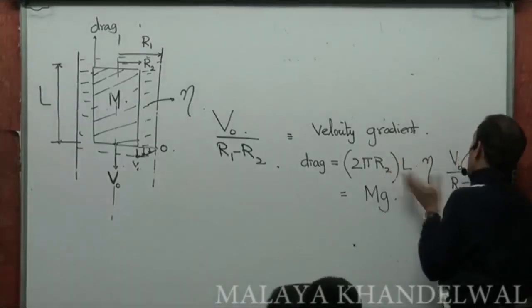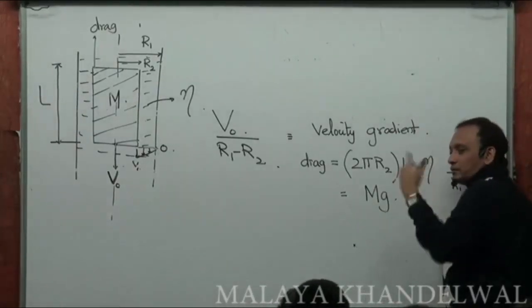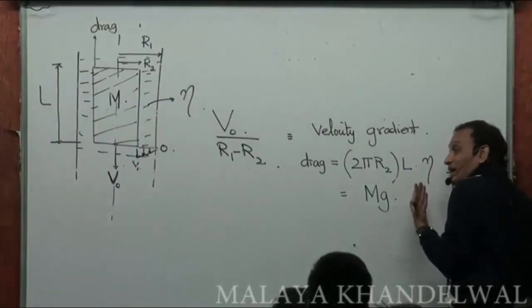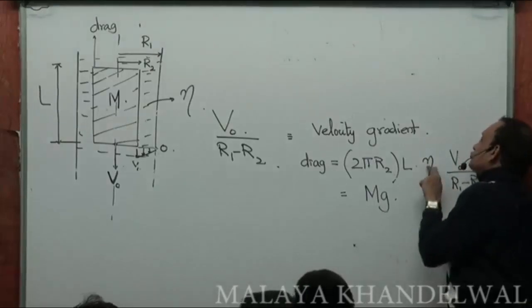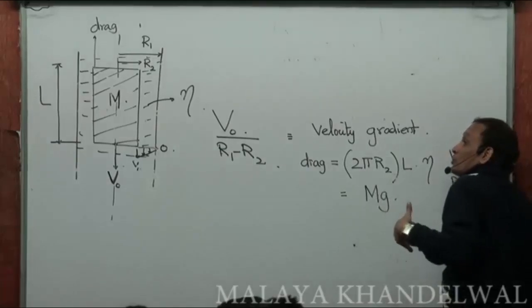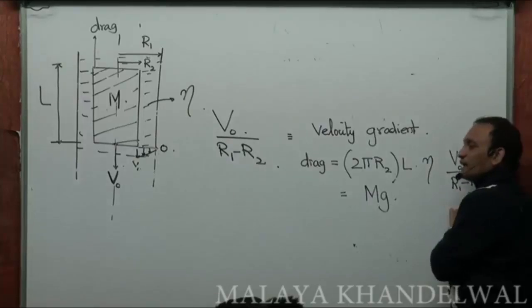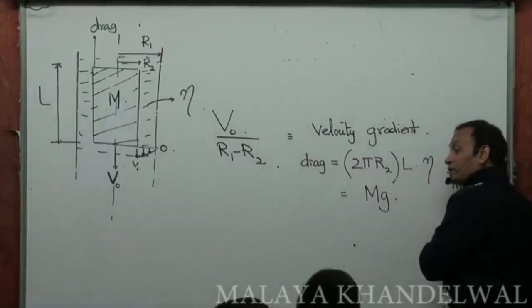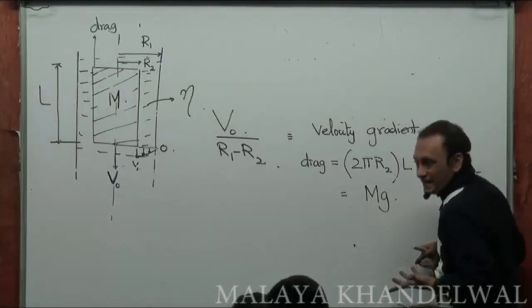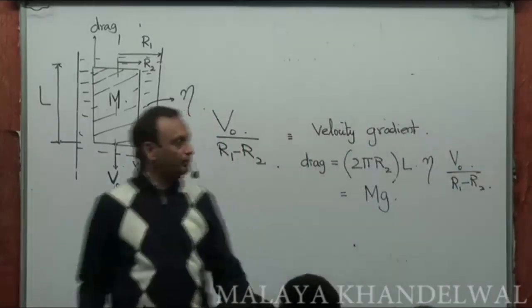So you may not necessarily be able to arrive at a liquid with viscosity as obtained by this. But then what you eventually do is you play around with R1 and R2, find the closest eta to that nature can provide, and then play around with R1 and R2 to obtain the available liquid, right? So then you find, well, eta you get as some value 0.1, say for example, but what is available is 0.15. So with 0.15, now you manipulate R1 or R2, one of these, and obtain the required geometry instead of obtaining the required liquid. You know what I'm saying? So this is what they do in design actually.